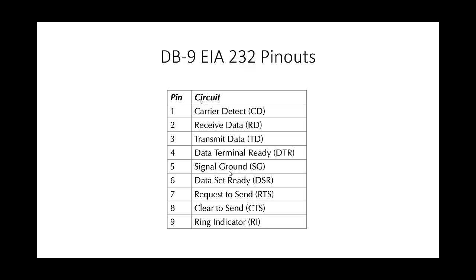It is possible to connect two DTEs together via a serial link without using a modem. This is often convenient for transferring files between PCs which are not attached to a LAN. You can do this using a null modem cable. The simplest form of this consists of two female DB9 connectors with the transmit pin, pin 3, of each connected to the receive pin, pin 2, of the other, and the two signal ground pins, pin 5, connected to each other. It is the serial equivalent of an Ethernet crossover cable.